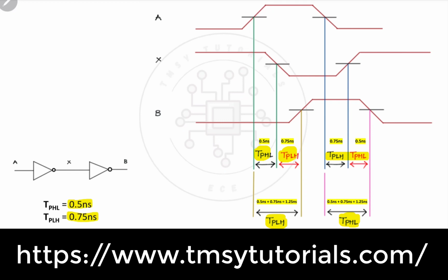So simply substituting here, we get TPLH as 1.25 nanosecond, and the TPHL value again 1.25 nanosecond. Why? Because they are simply the summation of these two values. So this is how we can calculate propagation delay for any given combinational circuit, or for any kind of gate.